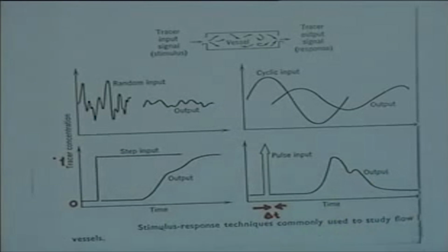Theoretically the product in a plug flow reactor must come out exactly after the residence time of the feed stream, but very often because of deviation from ideality of plug flow behavior, it might come out in a slightly broad zone. Some of you must have done chromatographic experiments, where very often broadening of the output is one of the major problems.